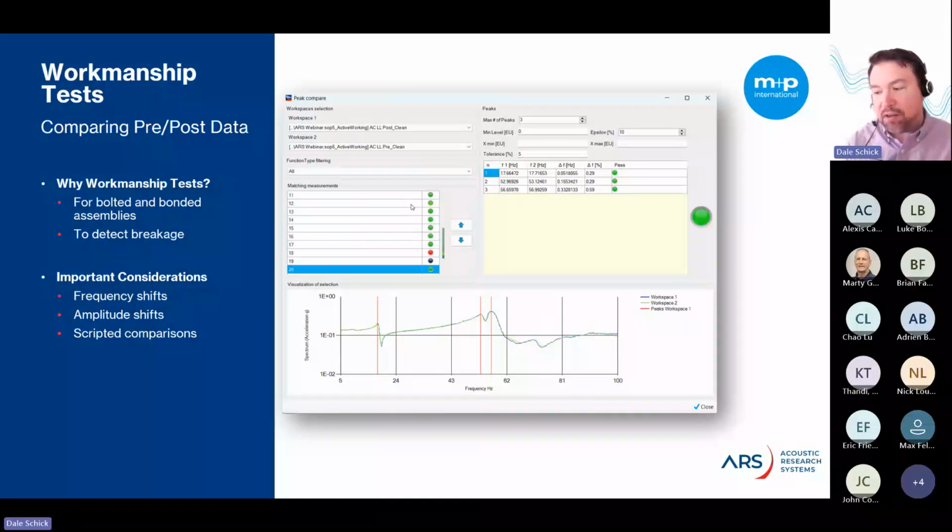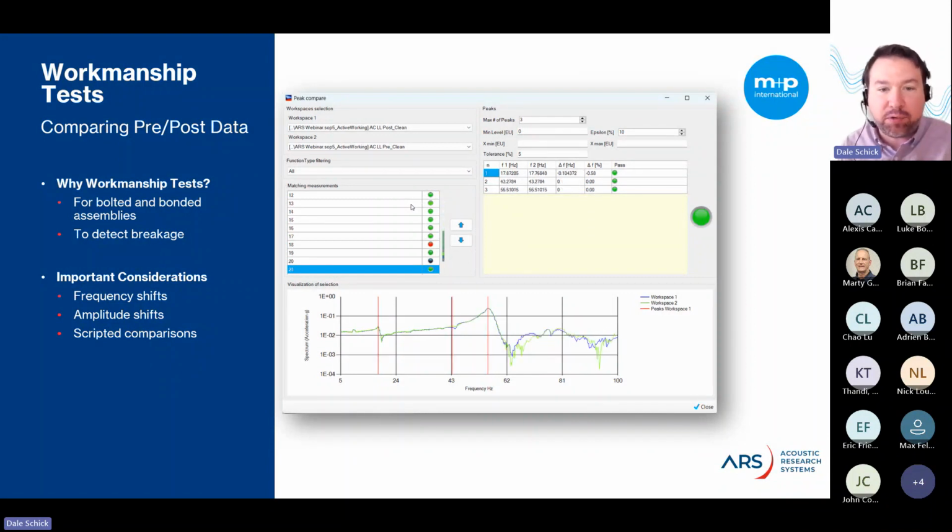Now, I think the exception there is for sine burst testing, where if you have a lateral launch load on your spacecraft, you have to simulate that some way on a shaker table. But if sine burst is not required because you're launching normal to the mounting location, you might be able to get by just doing an acoustic test. And the way this system is designed is that we could actually configure it with just say three devices for a small, like 12U CubeSat, for instance. So it's actually possible to do these tests pretty low cost.